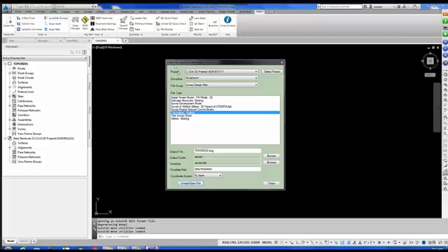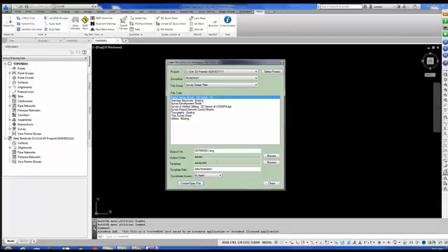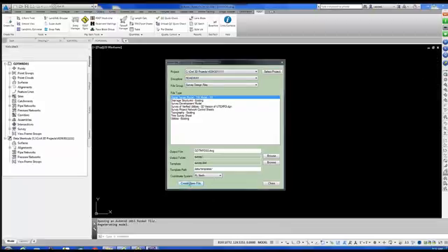And since I'm in the create file dialog, I'm going to pick on the digital terrain model. That's my GDTMRD file. All right, because I didn't exit the survey design file dialog, the coordinate system is already set, I'm going to pick create and open the file.